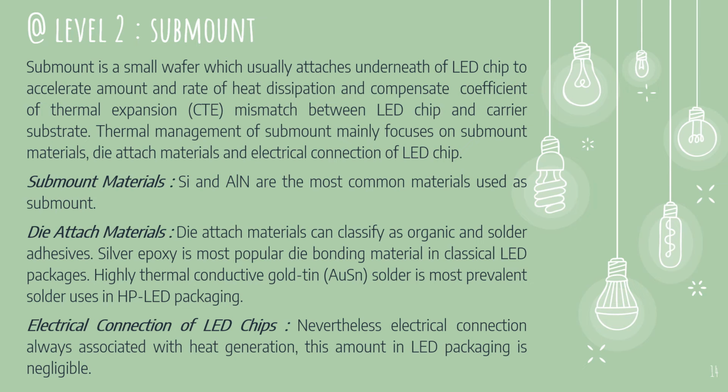While the die-attach material can be classified as organic and solder adhesive. Silver epoxy is the most popular die bonding material in classical LED packages. Highly thermally conductive gold-tin solder is the most prevalent solder used in high-power LED packaging. Nevertheless, electrical connection is always associated with heat generation. This amount in LED packaging is negligible.